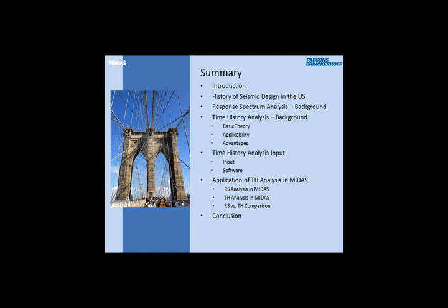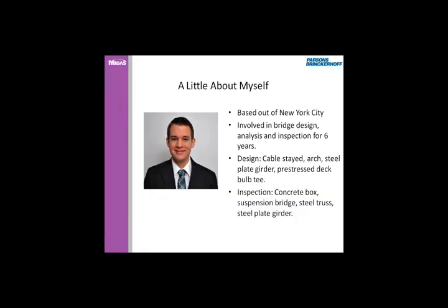Next will be, where does the input come from for time history analysis? There's a lot of people questioning where this data comes from. So I'll be talking about where the input comes from and then the software that can be used. And then finally, I'm going to show how a displacement time history analysis can actually be performed in Midas. At the end, I'm going to compare my results between response spectrum analysis and time history analysis. So I'll go over both of those in Midas.